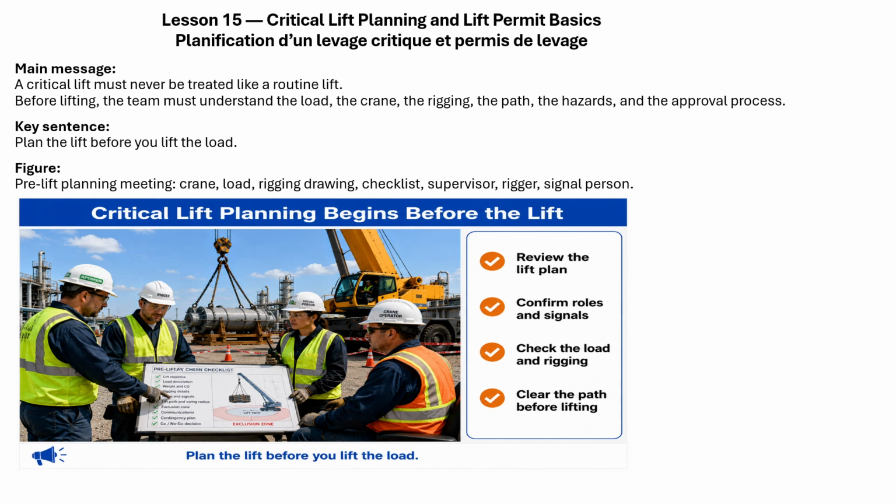Welcome to Lesson 15, Critical Lift Planning and Lift Permit Basics. Main message: a critical lift must never be treated like a routine lift. Before lifting, the team must understand the load, the crane, the rigging, the path, the hazards, and the approval process. Key sentence: plan the lift before you lift the load.